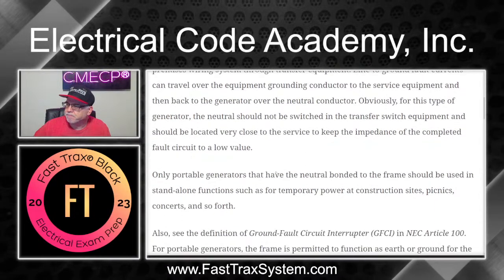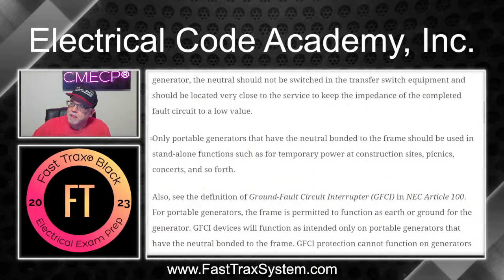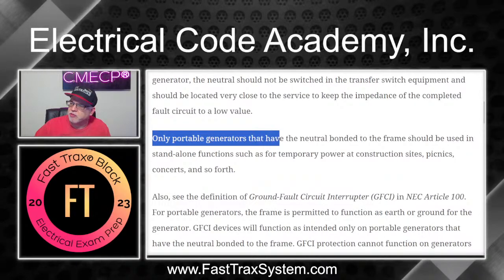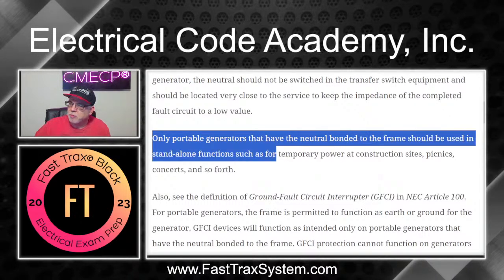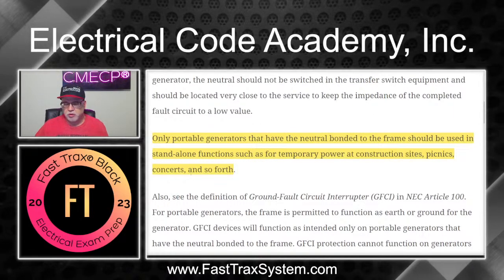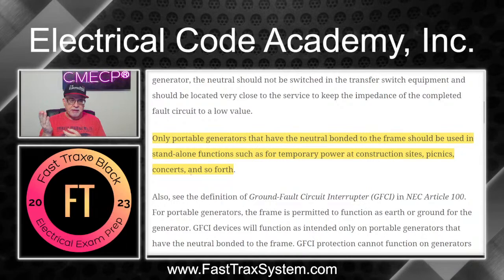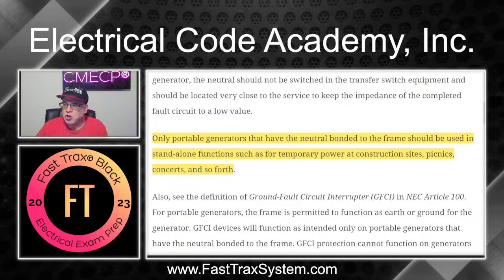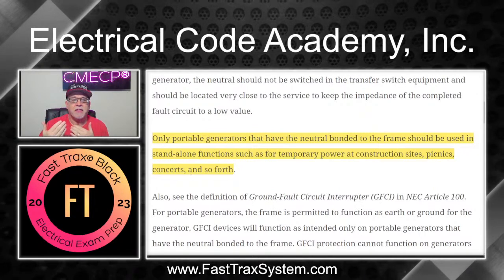Now, only portable generators that have a neutral bond to the frame should be used in standalone functions such as temporary power to construction sites, picnics, concerts, and so forth. So if you're buying generators for any of these applications, temporary power, construction site, pull it up, run the job site, you want to make sure that you have one that has the neutral bonded to the frame. So you want a bonded generator, okay? If you take anything away from this, that's what you want.